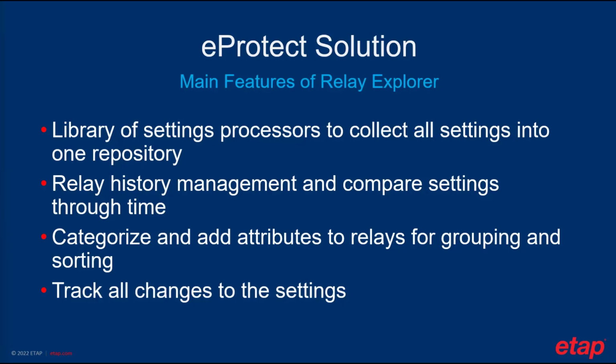So you can look at who's done what, what the settings were in the past, and what the settings are now, and you can compare line by line, see exactly what's changed through time. Say, what were my settings for this relay 1 year ago, 6 years ago, yesterday? And you can compare that on the web user interface.